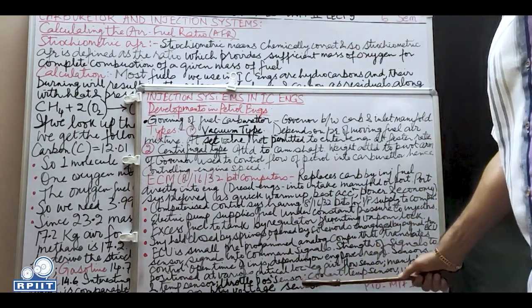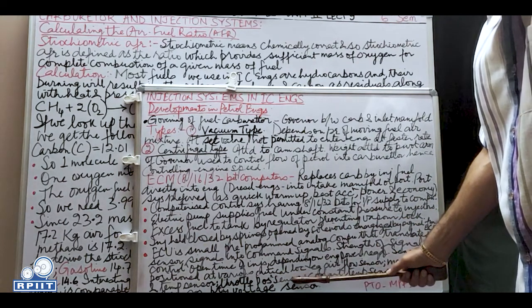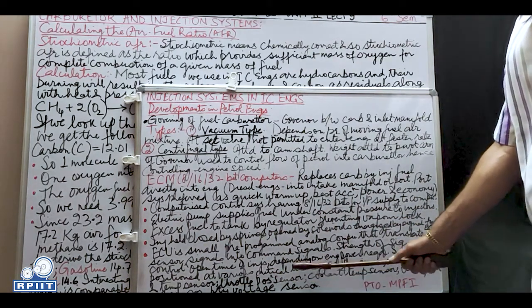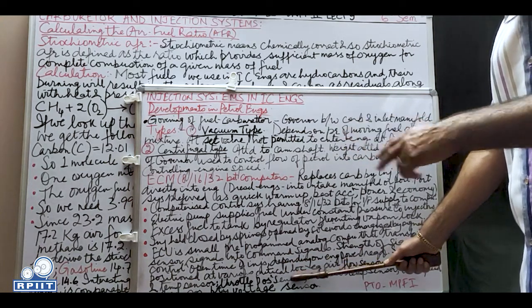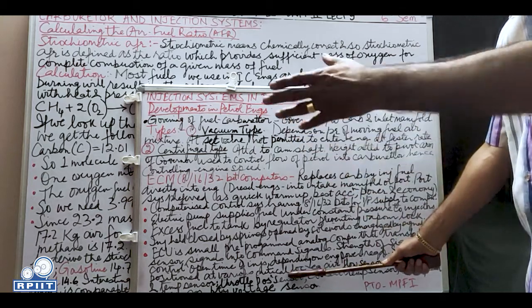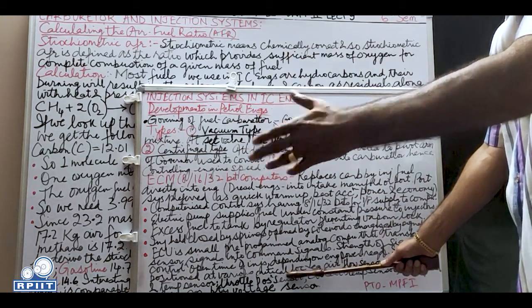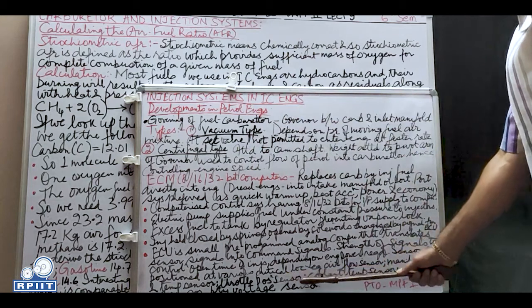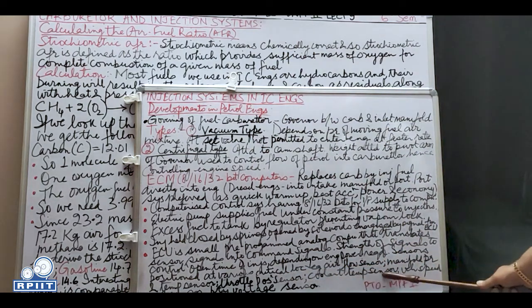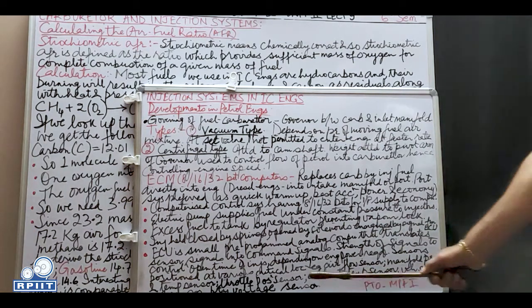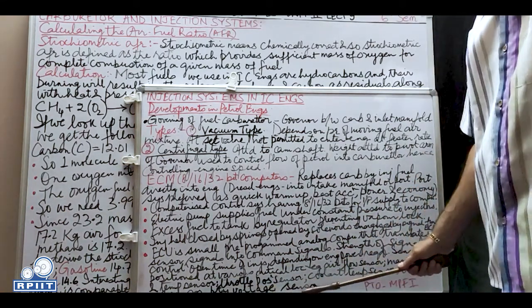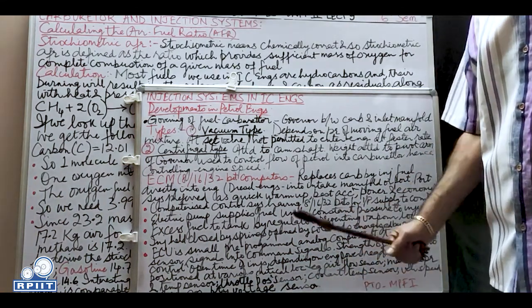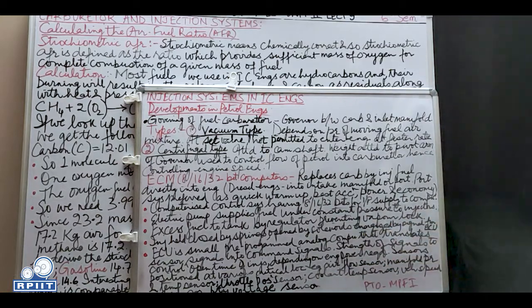Throttle position sensor: near the throttle there is a sensor which senses whether the throttle is more open or more closed. That signal has to go so that the ECU takes it into consideration. Coolant temperature sensor near the radiator. Vehicle speed sensor, this is at the wheels. Battery voltage sensor at the battery. The amount of current also has to be controlled.